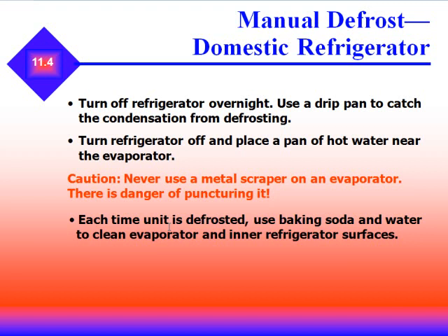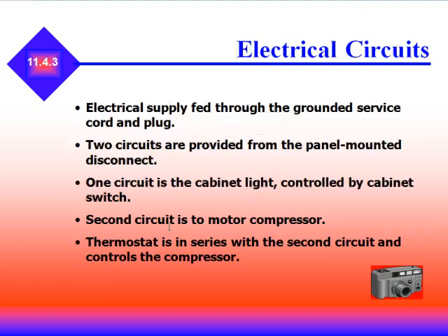Never use a metal scraper on the evaporator surfaces. There's a danger of puncturing it. Each time a unit is defrosted, use baking soda and water to clean the evaporator and inner refrigerator surfaces.